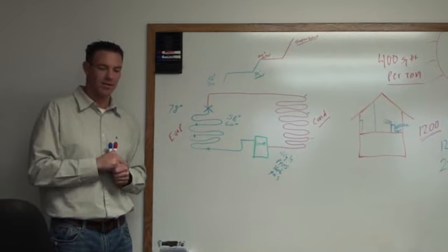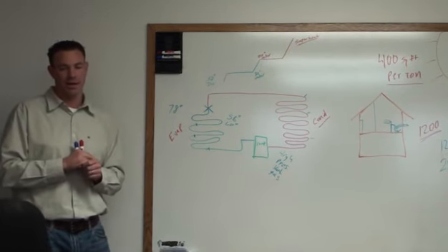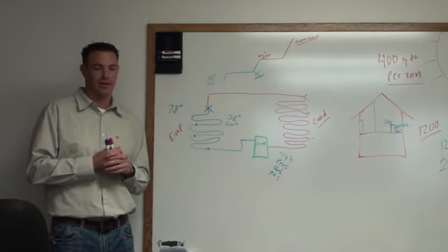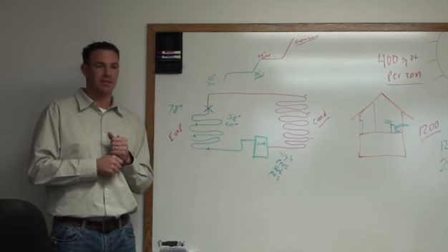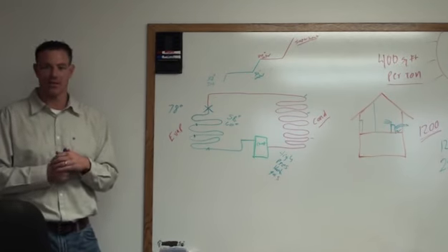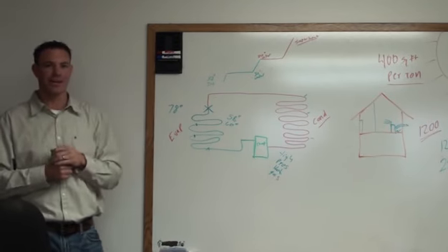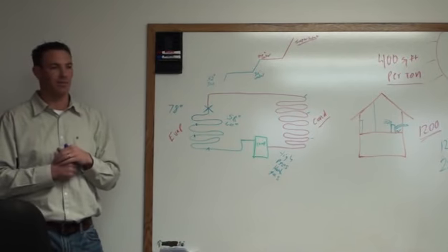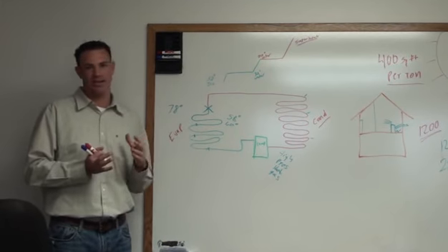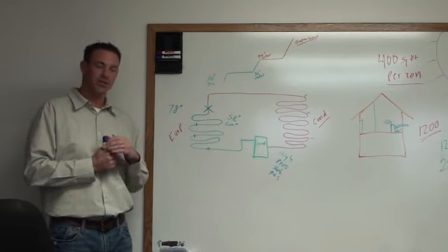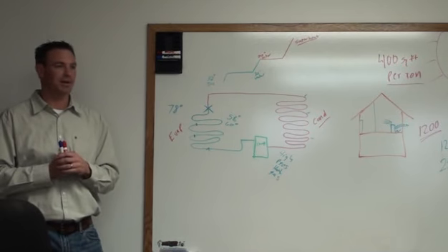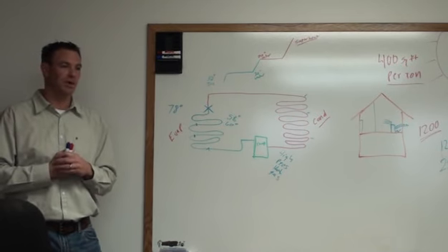Something else that's going to probably pop up and we're going to have to deal with, even more so than the heaters, is electrical wiring and amperage and voltage. It's going to be really important that we have the proper wiring, extension cords, and those kinds of things. You want to have the air conditioning unit plugged into a dedicated outlet at all times and any time possible. In other words, we're going to not get enough power to the compressor, and it's got a lot of safety features built into it, so it should cycle itself off if it overheats, but there are those times if somebody plugs it into a long extension cord, we could have problems with compressors.